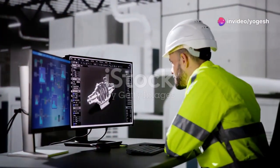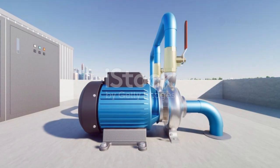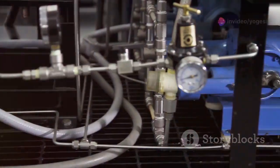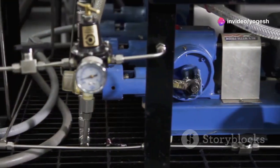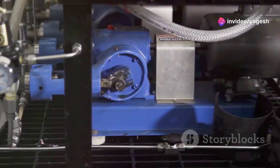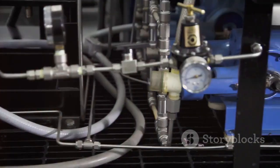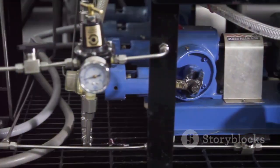Let's see datum targets in action with a pump casting example. The casting's rough, uneven surfaces make it impossible to use the whole bottom as a datum. Instead, we specify 3 datum target points, A1, A2, A3, on the bottom, spaced far apart for stability. These define the primary datum plane for fixturing.